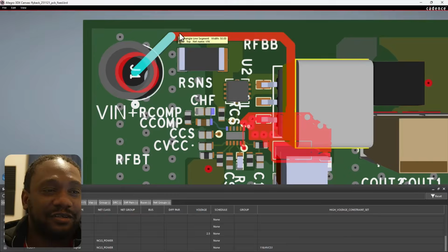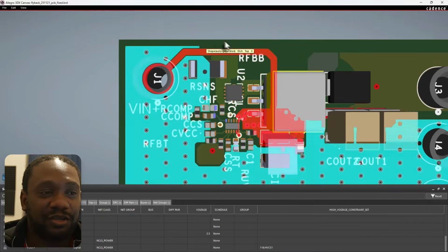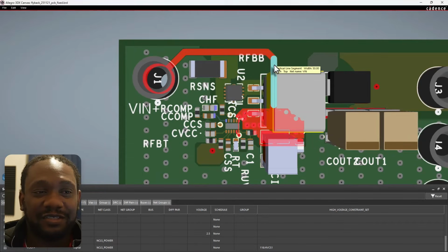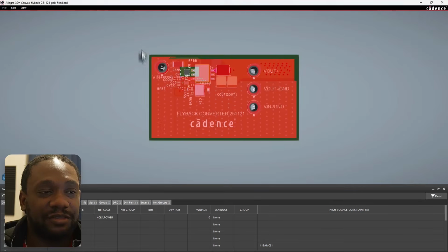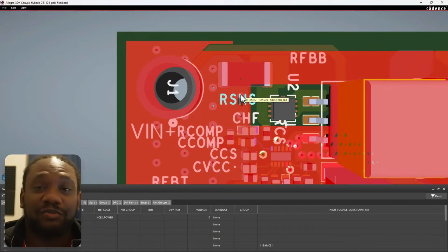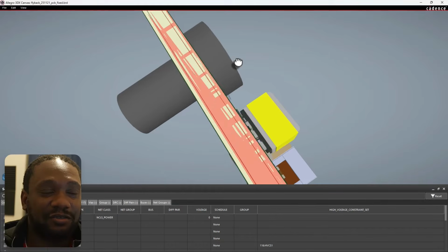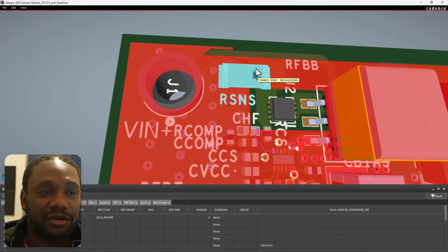Now this could be a lot closer. I could minimize this by moving this connector straight on top of that transformer. And that's ideally what I should have done, but it's just to show you, you don't want to do this, have this unnecessarily long. That's not good. Okay, but underneath there, I make sure to drop as much ground or return path underneath on layers 2 and 3, especially layer 2, underneath that hot loop.